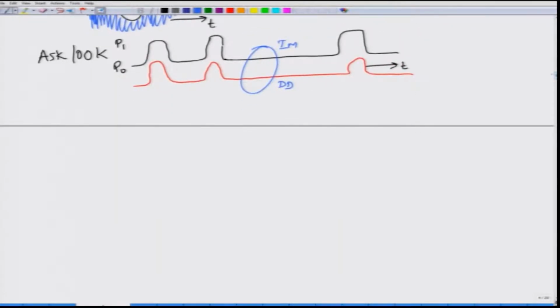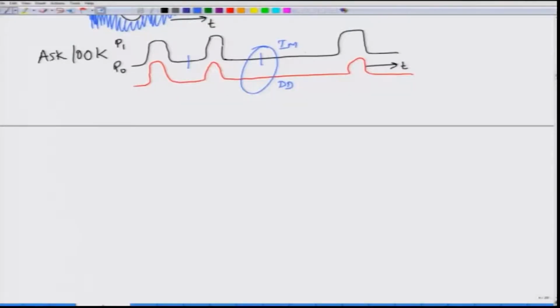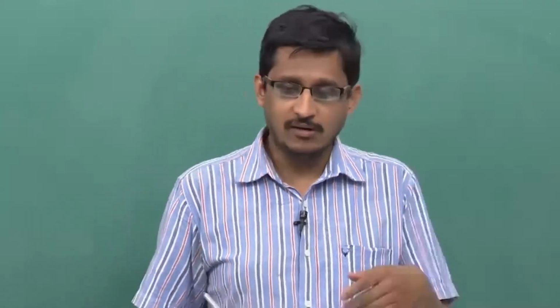You have to notice something else. There was absolutely no mention of the phase. So, as long as I am able to determine the bit boundaries, which is known as the synchronization problem, I do not have to know what the optical phase is here. In fact, my detection method is insensitive to optical phase. So, this is the direct detection which is completely insensitive to optical phase.